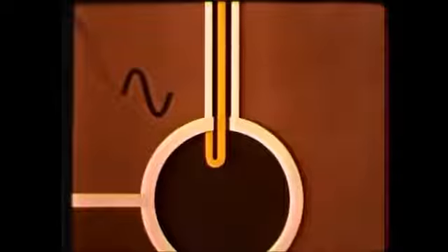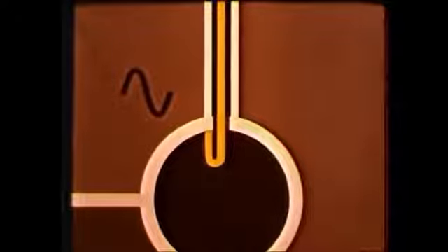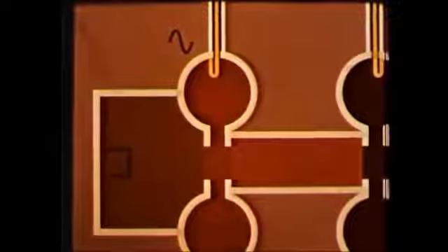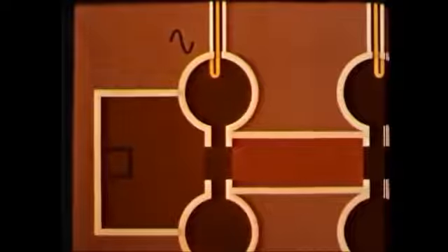Therefore, in the region between the first resonator and the collector, the electrons would have a constant speed if it were not for the influence of the cavity resonators. In reality, the first cavity resonator is supplied with the weak high-frequency signal which is to be amplified. This signal will initiate an electromagnetic field inside the cavity. Due to this field, the velocities of the electrons passing through the first resonator are modulated.